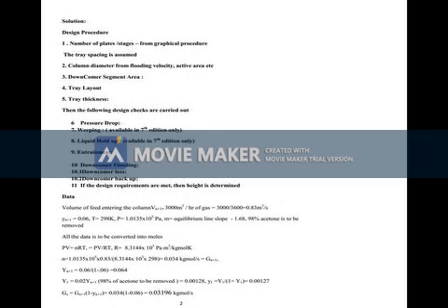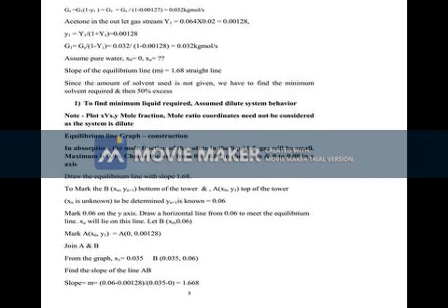The diameter of this plate will be 70 to 80% of the tower. The gases from the bottom will go through the holes, and the liquid will come through the downcomer and flow across the diameter.